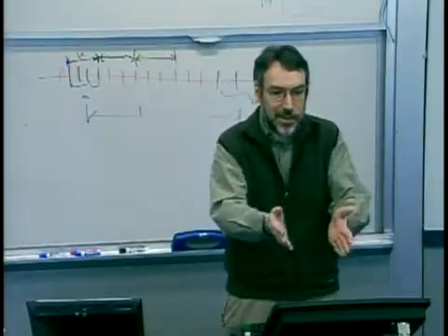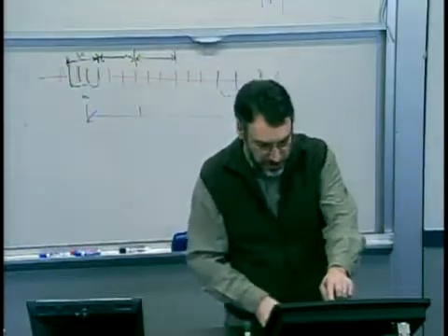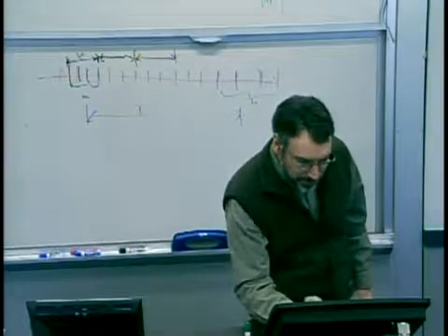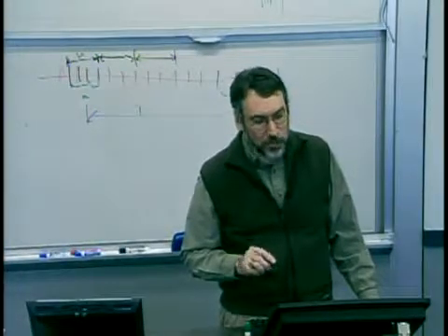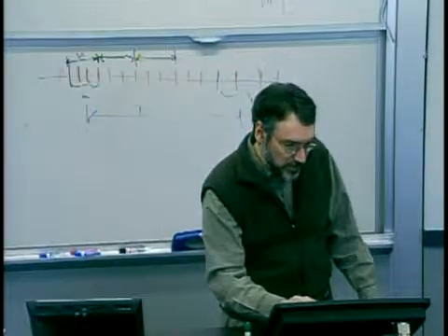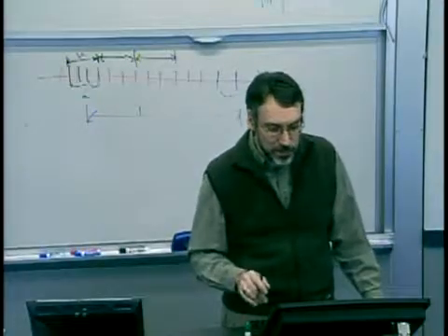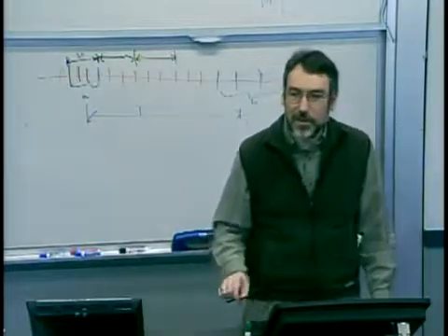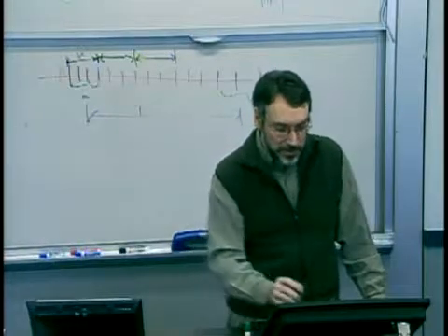But you're doing exactly the right thing, going back to some of the discussion we had earlier, of looking for additional evidence. If I got this alarm, I might look back and say, the previous points, there's an awful lot of them to one side of the mean, and in fact maybe a drift, although this point looks counter to the drift. So there's a little counter evidence. By the time I get to this point, I'm starting to get really convinced that something is weird, right? Because now look at this.